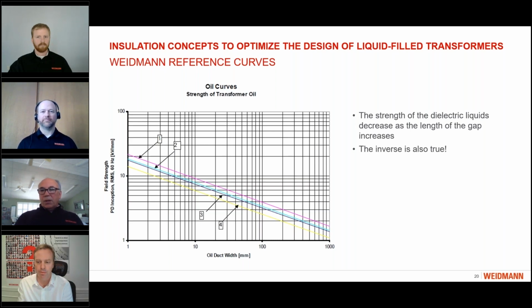We publish strength curves in oil as well. And Jason talked to this a little bit at the first question about what the strength is of insulation materials. It's difficult in that you have to understand that the strength is measured according to a standard in a laboratory, and that strength is very dependent on the test method itself. In Brad's lab, he has different electrodes according to whether it's an IEC or an ASTM standard.